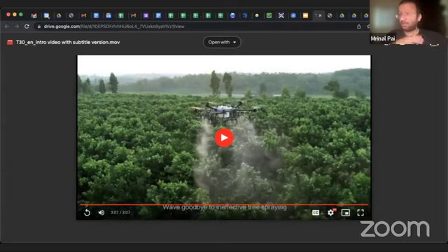In 10 minutes, depending on the capacity of the drone, it can spray anywhere from an acre and a half to up to 4 acres, right? 3 to 4 acres, depending on the size of the drone. Smaller the drone, smaller the capacity per battery, per flight. And the larger the drone, larger the capacity, but anywhere from 1 to 4 acres per 10 minutes per flight is what these drones can spray.